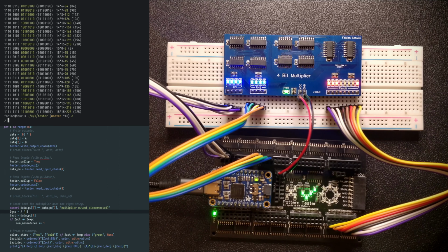And so this notion of having a piece of hardware run and then have a piece of software basically be a programmatic description of what the hardware is supposed to be doing, that's called golden model testing, where the thing we have in software is called the golden reference model, which someone has written up, and presumably it was easier to write that thing than to come up with the hardware, because for example in Python it was trivial to just type the star operator to mean multiplication, but the hardware was pretty difficult to assemble because you need these adders, you need these AND gates, and you need to mask certain things out.